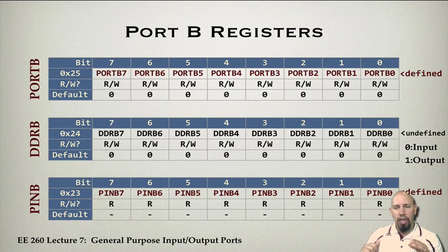If you were to try to do this in the Arduino IDE, you'd have to go pin by pin, and that would take 7 commands. So, as you can see, being able to work with the ports directly is much more efficient, speed-wise, than doing it with the Arduino IDE. We can already see that by going to the registers, we can streamline our code much more.